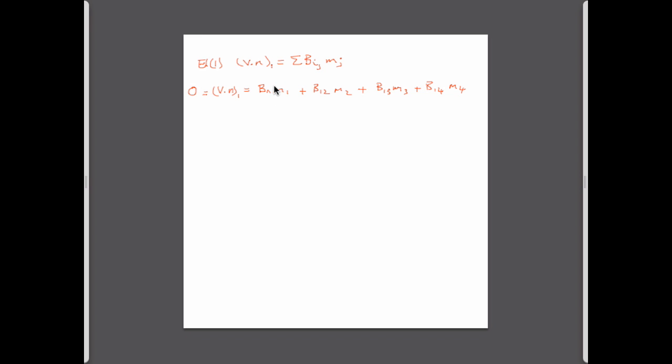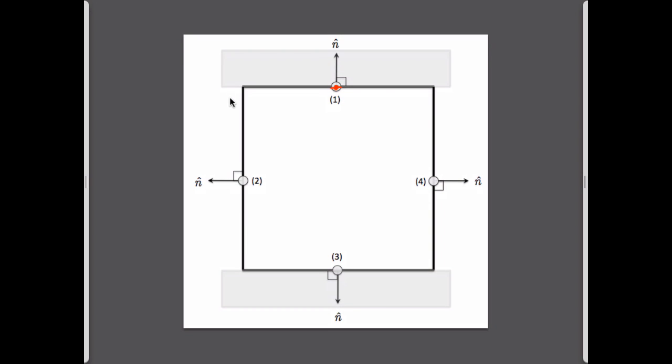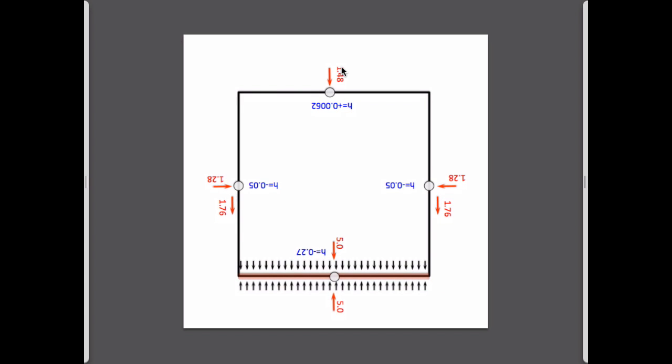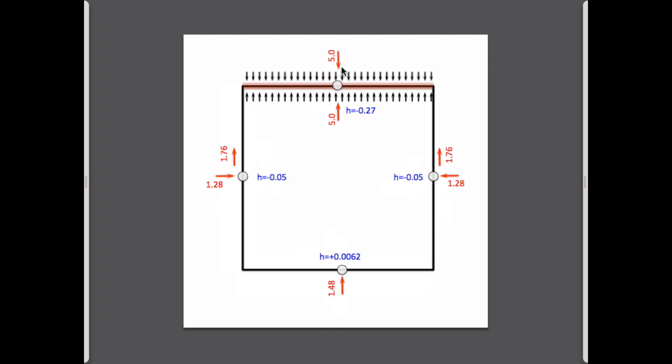And so we have to figure out exactly what these are. This is by putting a source on the element in question and looking at its self-influence in terms of the velocity it induces. So we're going to put a source on this point here. I'm going to draw this and scribble it off, and we're going to see what the velocity is that it induces at this point. So we put a source at that node, the velocity normal to the boundary.